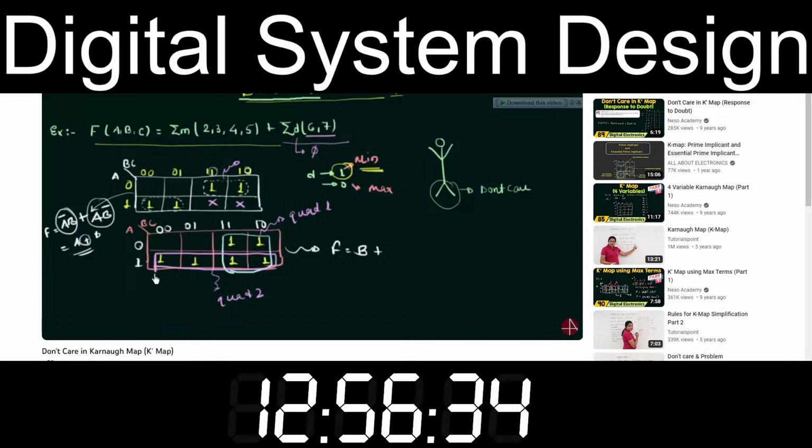In this quad 2 you can see that B and C both are changing from 0 to 1, and A is 1 and it's not changing, so I will write it as A. So the same function can be written as A XOR B, which is A complement B or AB complement.